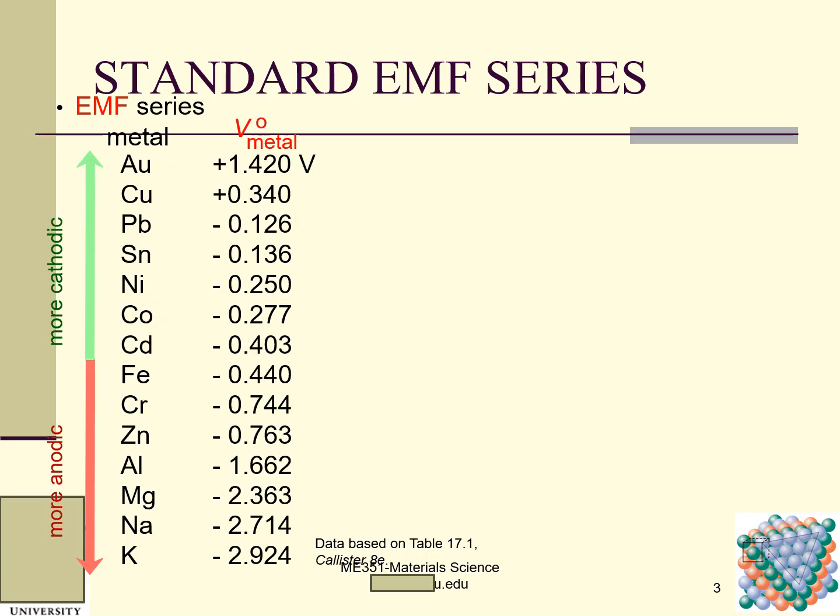As I told you, cathodic means that they capture the free electrons, and anodic means that they give up the electrons. By giving up electrons, the metal atoms can become ions and then dissolve in the solution. This can result in corrosion.